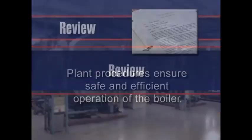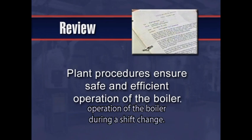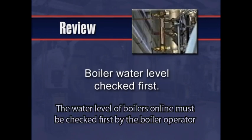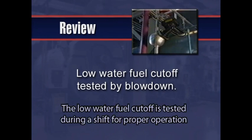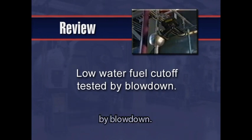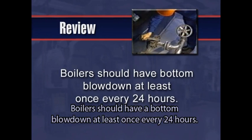Review. Standard plant procedures are established to assure continuous, safe, and efficient operation of the boiler during a shift change. The water level of boilers online must be checked first by the boiler operator taking over the shift. The low water fuel cutoff is tested during a shift for proper operation by blowdown. Boilers should have a bottom blowdown at least once every 24 hours.